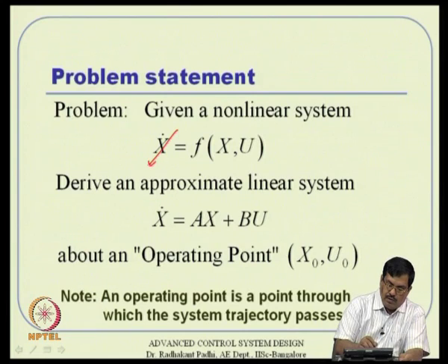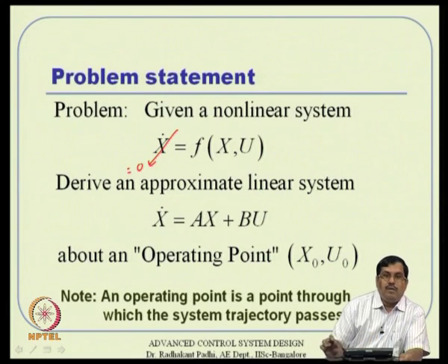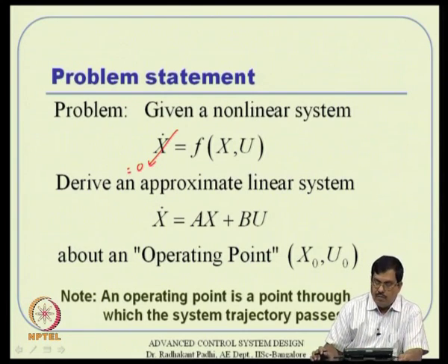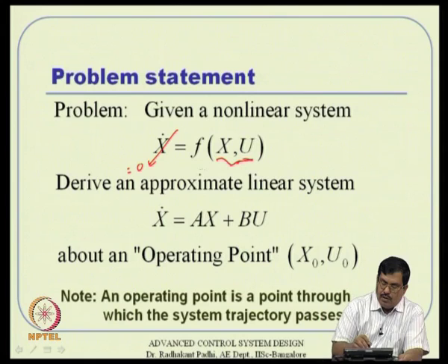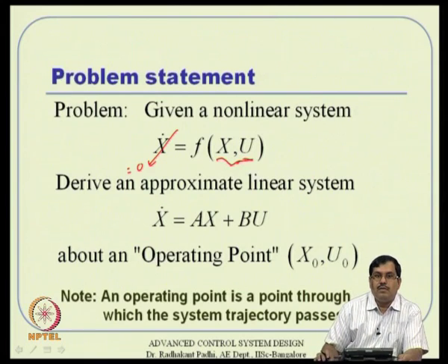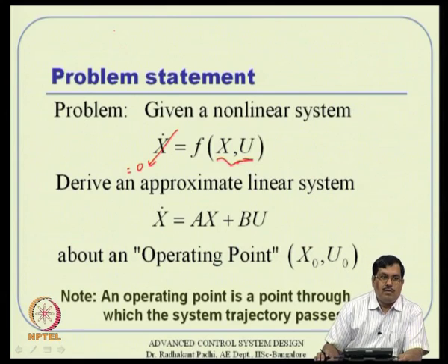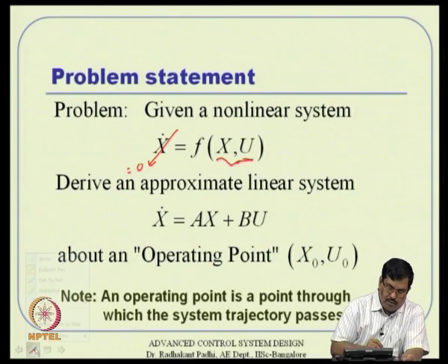just put this equal to 0, x dot, because that is the definition of equilibrium point, and then associated with that we make some assumptions. This will result in, let us say, n equations, with n dimensional x. But x is n dimensional and u is m dimensional, remember that. So, we need to have m further assumptions for that, so that the number of equations and number of variables will be equal, from which you can solve this system.